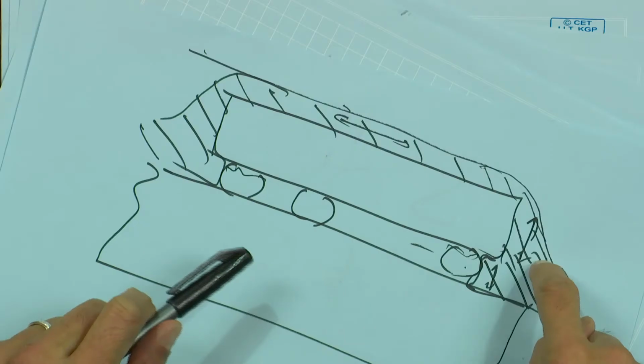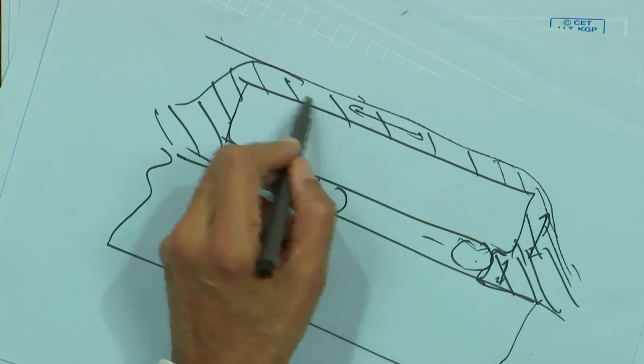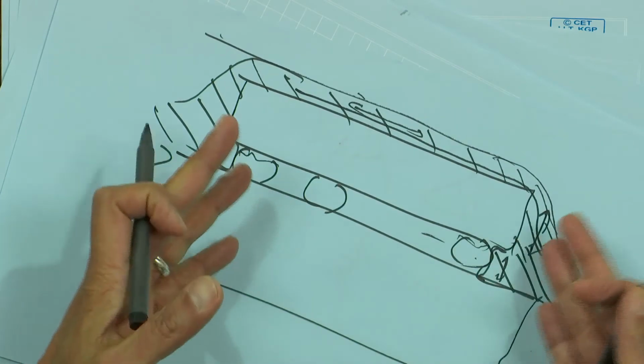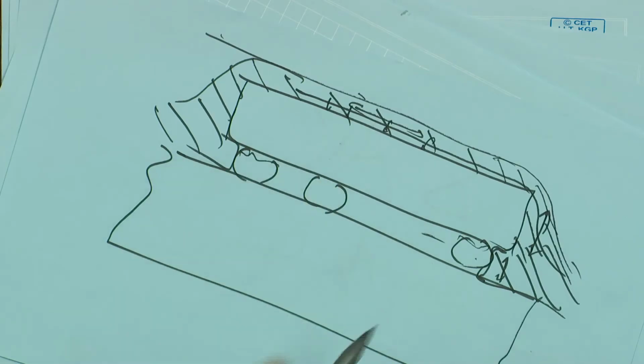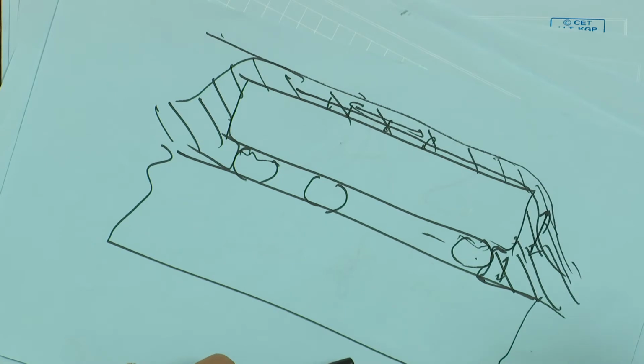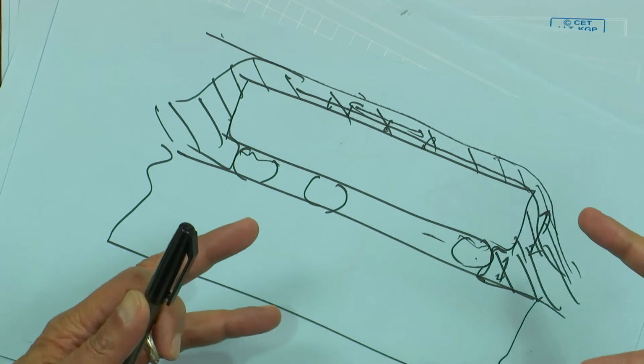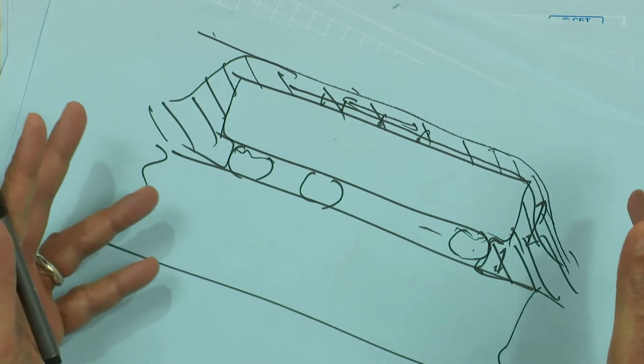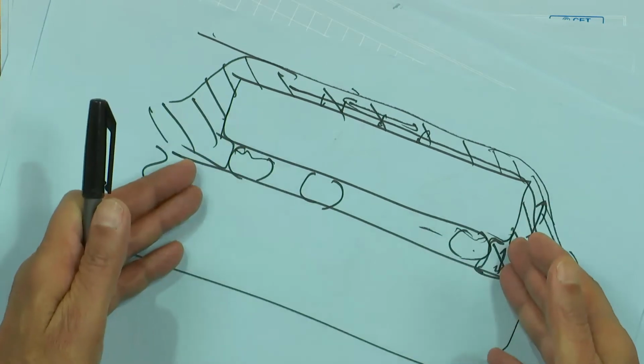Okay? So that means your conformal coat material must not be too thick. It should be as thin as possible. Well, not as thin as possible, because if it's too thin, then it cannot protect from moisture. Moisture will take very little time to penetrate through that. It must be of materials that have low moisture permeability. It must not have too high a mechanical stiffness, Young's modulus, and it should not have too high a CTE. The CTE should be matched to the assembly.